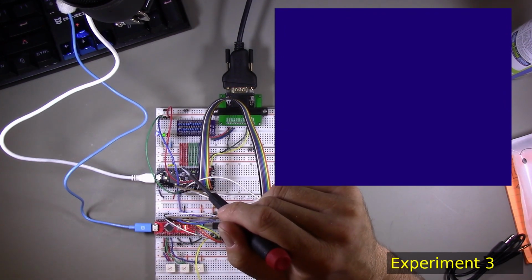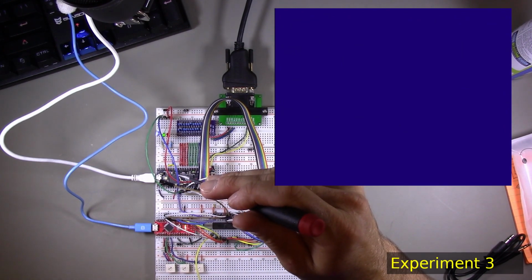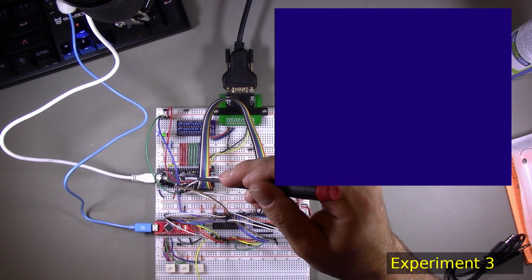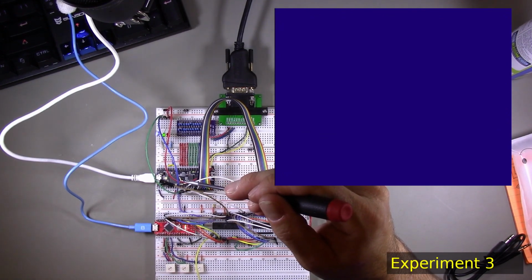the control logic, the signaling that indicated when a byte was received, was not implemented correctly. There was a bug in it, and basically what would happen is that the state machine that processed the data that was in that 1-byte FIFO would see each byte of data twice.